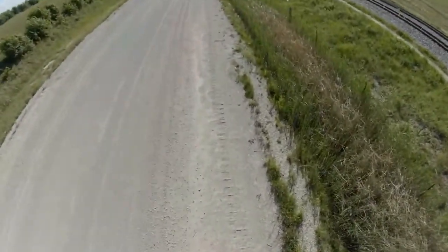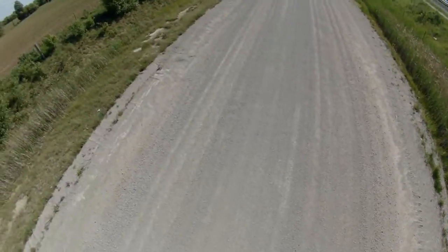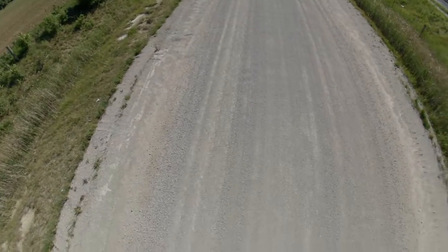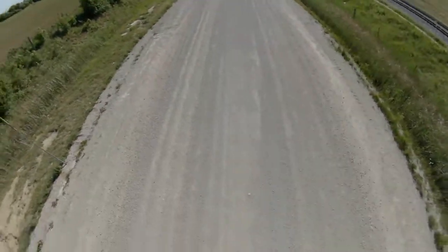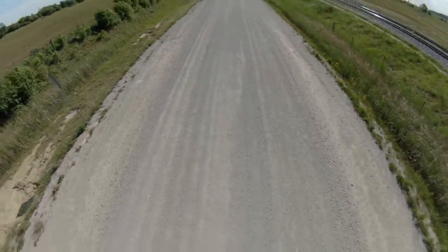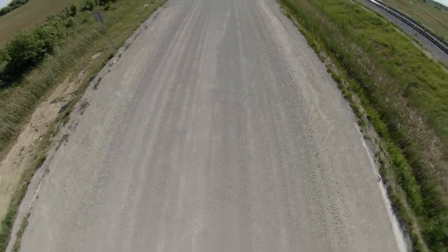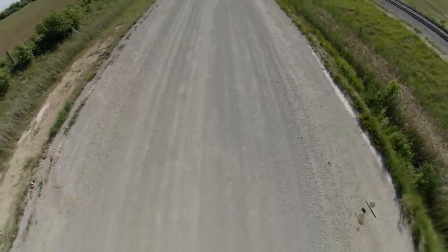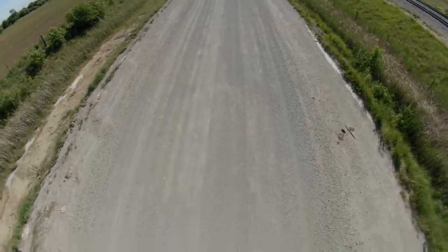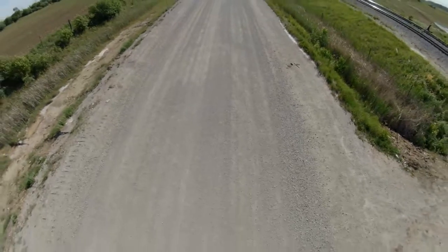Another approach that you could use here would be to walk straight up and down the roadway 3 times, starting on the left side of the road, then starting on the right side of the road, and then once in the middle, and you'd have 3 sets of overlapping images. Now, if you walk just straight down the road and you just try to use one set of images, it's not the best. What you want to do is try and have it like you had 3 cameras going down the roadway at once.